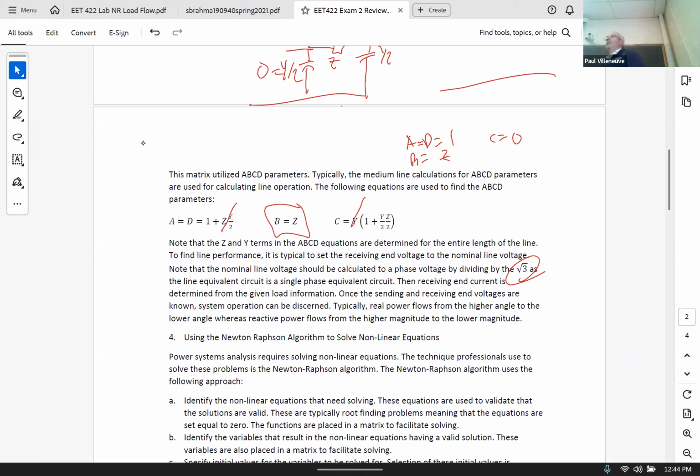That is applicable if the X over R ratio of your system is pretty high. In all the problems that we've done in class, except for your homework problem where you had a Y bus that had real parts, there was no R value. But even in homework number 2, you found that you got a high enough value so that it would work.